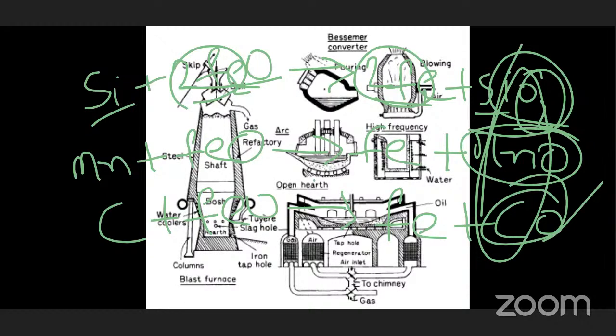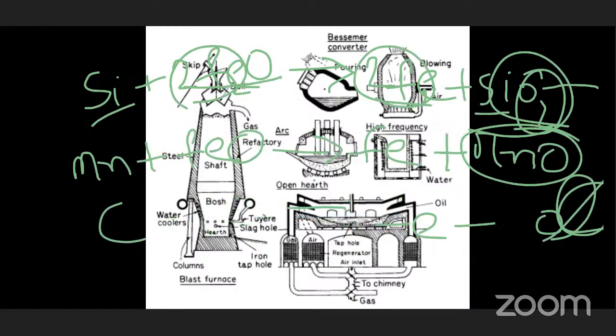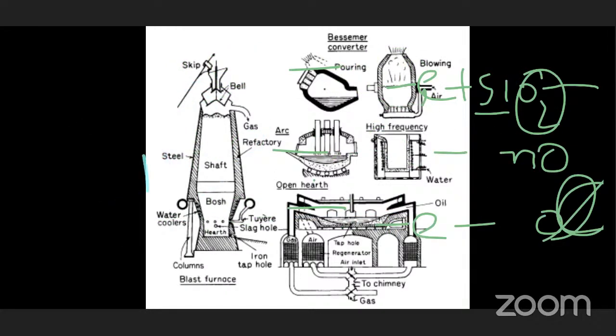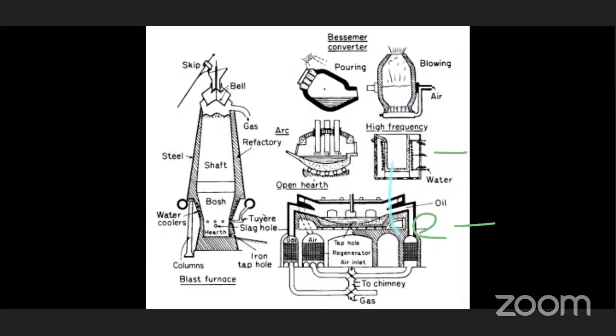So the refining sequence can be followed by observing the flame at the mouth of the converter. When we open the mouth, we see the carbon escaping. During the earlier part of the blow, when the silicon and manganese are being oxidized, the flame is short, yellow in color and of low luminosity. So the yellowish color is what we see, and from the color and luminosity we can judge the intensity. The yellow color represents the slag.